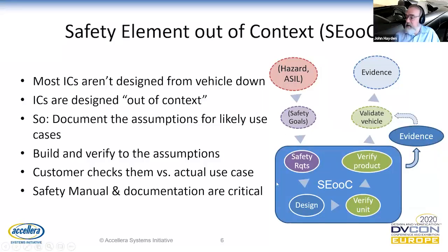And so we've tailored the process into this part in the blue rectangle here, where we document our assumptions as to what we expect the safety requirements are going to be, develop and verify to that, and produce our evidence as semiconductor providers or module providers that are then used by the next level up integrator in their safety case. So what's critical is that there's a good package of documentation that shows what the assumptions were that they can verify against, along with the safety requirements they must follow and the safety analyses. And that all is called the safety case.